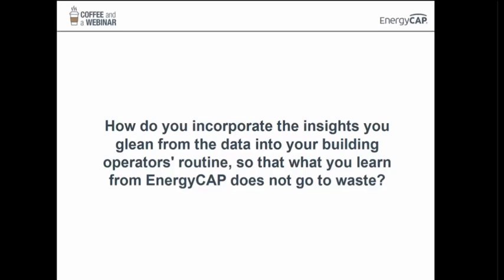Right. And as I mentioned in my presentation earlier, at this time we are not using EnergyCAP to do that specifically because we just started pushing our interval data into EnergyCAP. But in addition to the EnergyCAP program, I also mentioned we have a fault detection and diagnostic program through Iconics. And that's where we also push our data to their system, and their system has algorithms and rules that our energy engineers have written that allow us to flag any deviation from optimal operation and allows the control center that we have to respond to those as faults with prioritization.